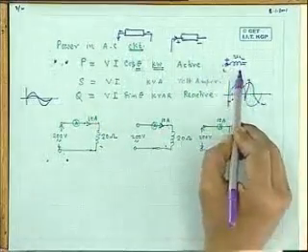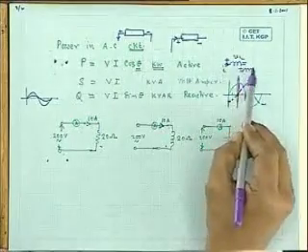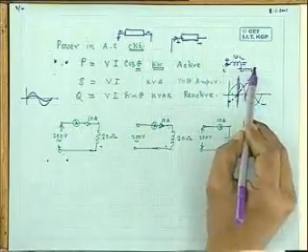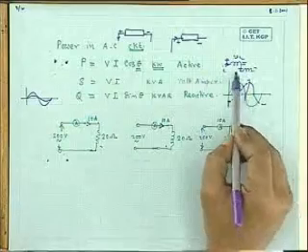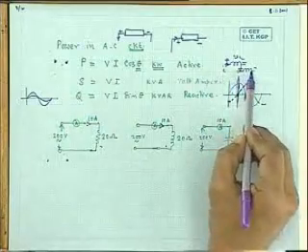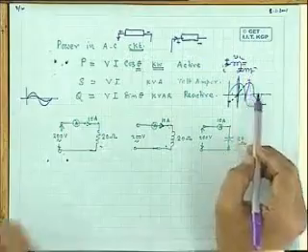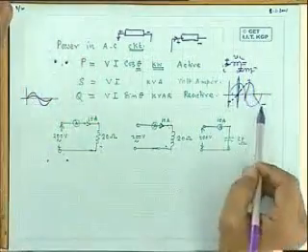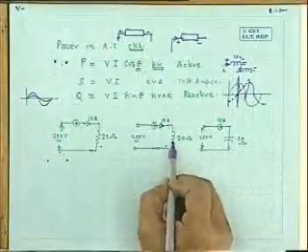Consider this instant. When voltage across the inductance is really positive, that is whatever I have assumed here, that is correct, and current is also positive, it absorbs power. So, over a cycle of 360 degrees, sometimes it draws power from the supply and the same power will be returned back at different time zones, that we can easily find out.